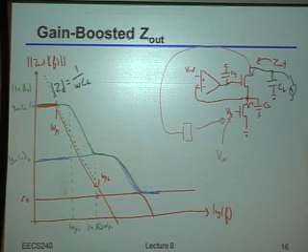Now, obviously, the bandwidth you're interested in depends upon how exactly you're using the rest of the circuit, right? Because, for example, if I tied this into unity gain feedback, that would have a very different constraint than, for example, if I just tied it in feedback with a gain of a half or a tenth or whatever the number would be. Okay? Does this make sense to everybody?